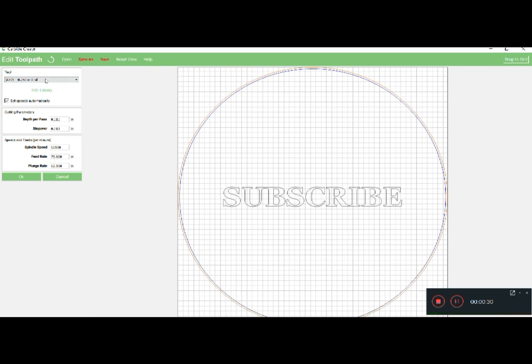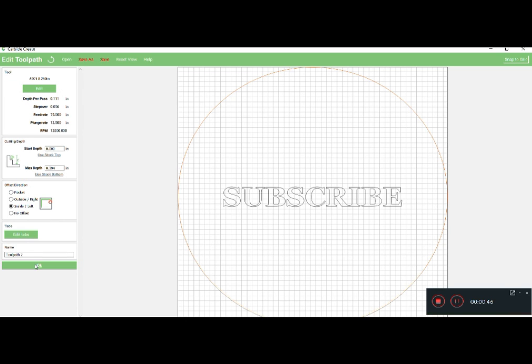But we do have this set up, right? The 201. We're going to set the speeds automatically. And a lot of people say, don't touch the speeds. Well, you sort of have to touch the speeds. So depth per pass. How far do we actually want this to go down? So let's hit OK first, and let's go to max depth. So basically, you have your 201.